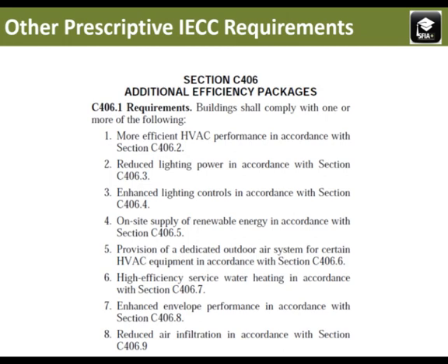However, if the level of continuous insulation is not acceptable, and you look to one of the other compliance paths to reduce or eliminate the foam, then these do have an impact. The 8 items shown here are some of the improvements previously available to trade off continuous insulation. With them now being mandatory, it reduces the flexibility offered with the performance paths in the IECC. ASHRAE 90.1 still retains a higher level of flexibility by comparison.